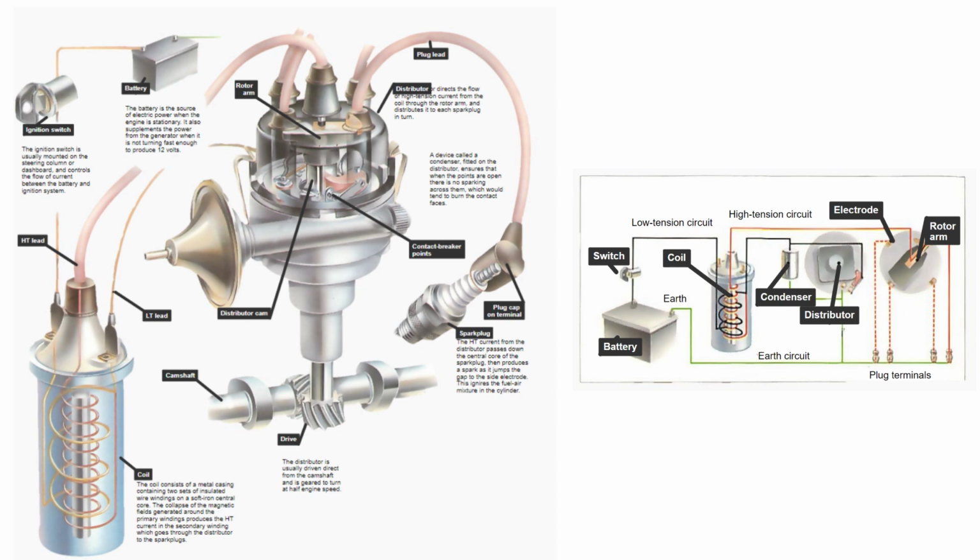The secondary winding has many turns made up of smaller wire. The enamel and layers of oiled paper insulation insulate the windings from the high voltage. The coil is fitted into a metallic can with high voltage insulated terminals and low voltage connections.